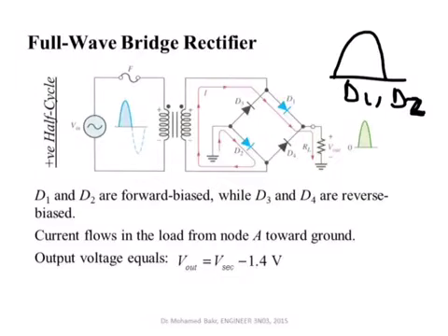So even though the voltage here is alternating direction, in the first cycle the current was flowing this way, so this is positive relative to this one. In the negative cycle, the current is flowing this way. Again, this is positive relative to this one. Then again, this is positive. So what is being seen on the outside across the load is something like this. It is simply a full rectification of the signal.